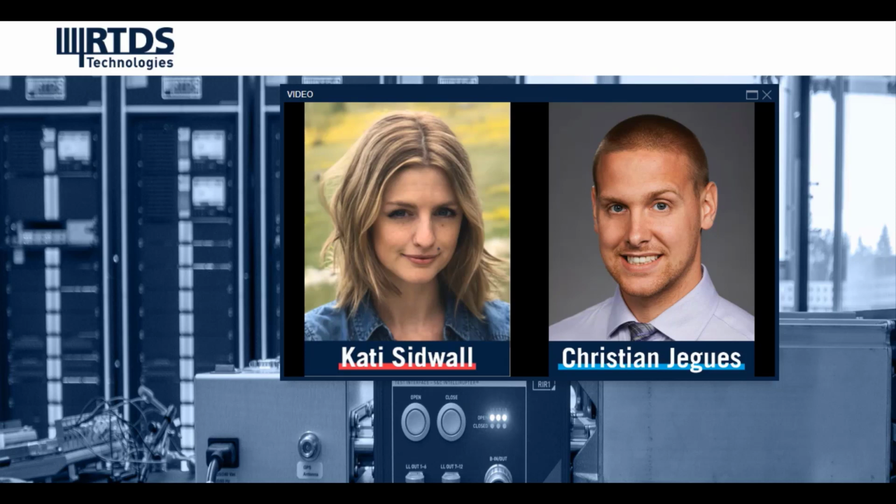That control module we actually removed from that assembly to use it in this testing. Instead of being connected into that base, it gets connected into the IntelliRupter test interface unit. And then again, the RTDS will inject signals into the test interface unit to test the protection settings on that control module. So that control module is no longer connected to the other hardware that the IntelliRupter would normally operate. That other hardware, like the switches, wouldn't be operating when we're testing the IntelliRupter with the RTDS.